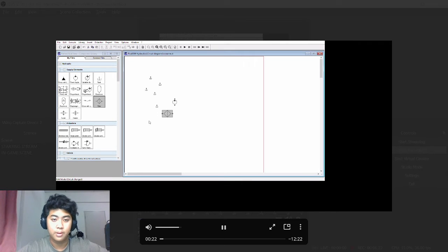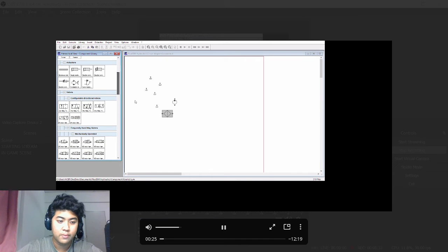After that, I will pick a filter, and the function of the filter is to clean compressed air and trap solid particles. And then I will pick a double acting cylinder, which is one where the thrust or output force is developed in both the extending and retracting directions.